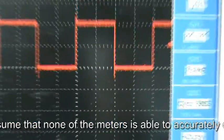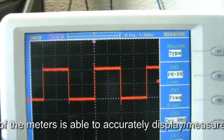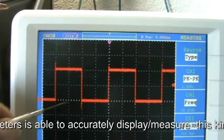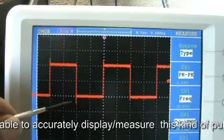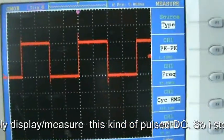The time base is 5 milliseconds per division. So the first positive pulse is 10 milliseconds, and the total period is 20 milliseconds.